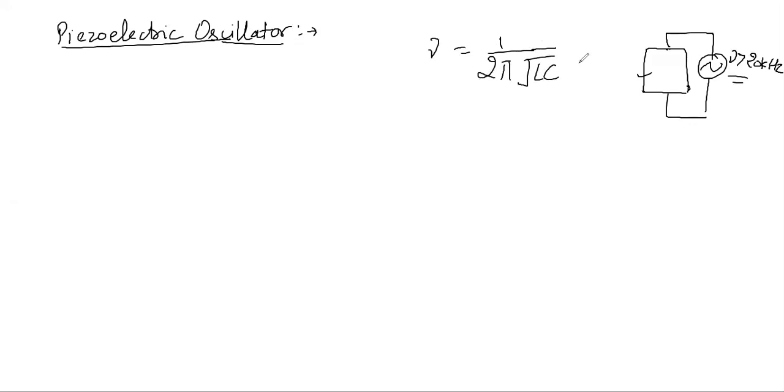So this is the frequency of an LC circuit, right? So I can control the frequency of the current and voltage by changing the value of the capacitance. Variable capacitors are easily available in the market here. So how can I do that? The simple procedure would be that I have an inductor, I have a capacitor here. Let's say this inductor has inductance L1, this capacitor has the value C1, then this would be L1 C1 here.